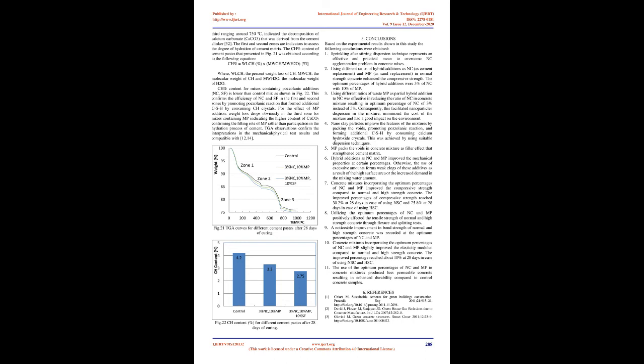Also, the sheets act as bridges connecting both sides of the crack together, preventing crack propagation, as shown in Fig 20. This interpreted the enhanced tensile properties of the optimum concrete mixes. Moreover, the applied dispersion technique, sprinkling after stirring, was efficient to avoid agglomerations of NC, as they were not detected in SEM micrographs.